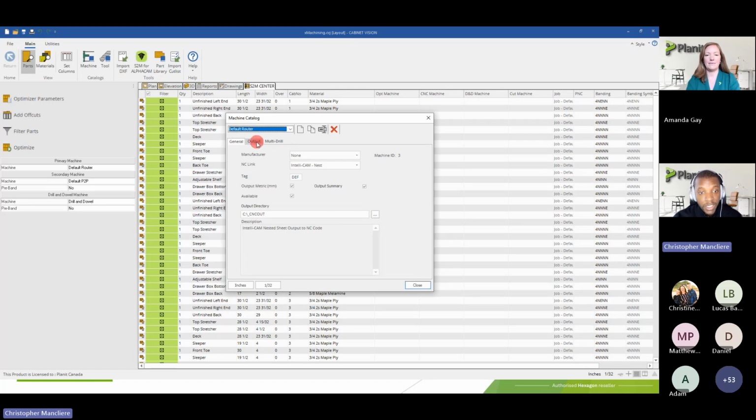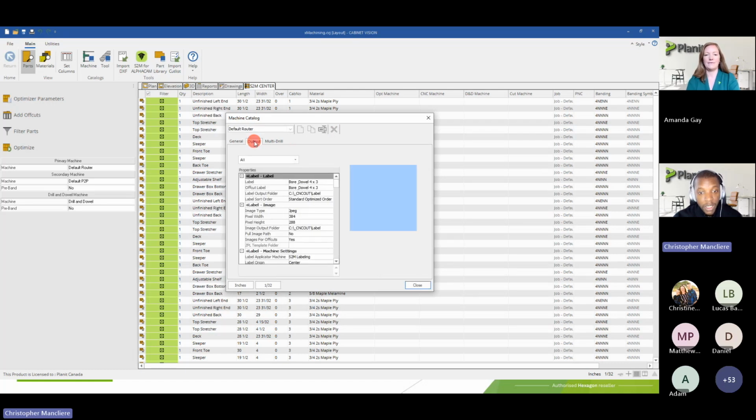The next thing is in the output tab. We'll cover really the most important thing to modify if you have an issue with your machining. Most of those settings are already set. So as I said, don't go and change everything here because you will have a dramatic impact on the way icg is outputting your file to this machine. But the one that's safe to change will be first in the nesting group. So in the drop-down list, I select nesting. The very first one you want to check is your nest type.